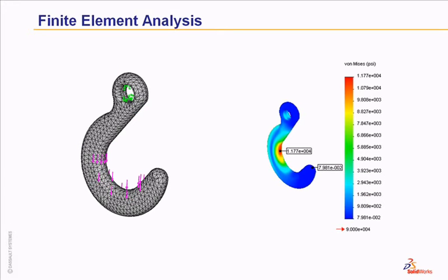In finite element analysis, often referred to as FEA, the body of your part is divided into a large number of sections called elements. The grid-like pattern of elements is called a mesh, and each intersection of the elements is called a node. By applying force on each node, FEA can determine how each node will react to certain stress levels. In SolidWorks, FEA is used to verify if the product will be able to handle the stress and strain placed on it prior to the manufacturing stage. For example, it allows you to visualize where your product bends or twists and indicates the distribution of stresses and displacements.